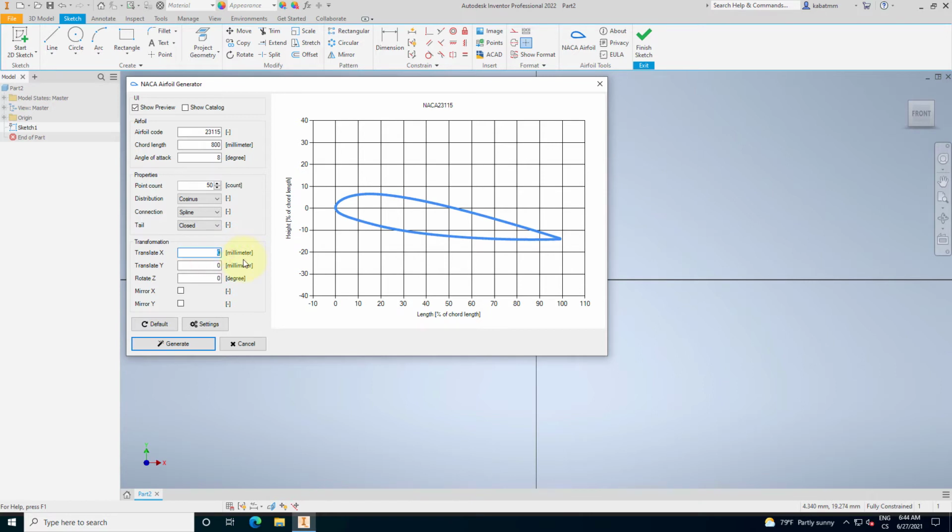Transformations are used for pushing a sketch to the right place. It's really helpful if you are building some complex shape like a wind turbine blade, etc. Rotation is a little bit different from angle of attack, because it is executed after the translation. Angle of attack rotates the geometry before the translation, that's the difference.